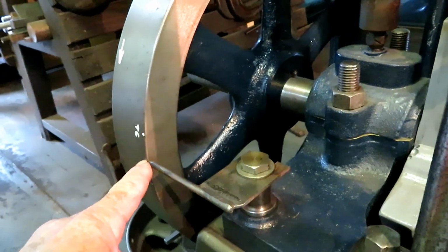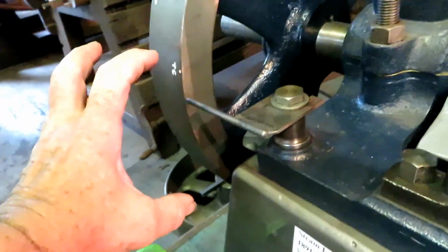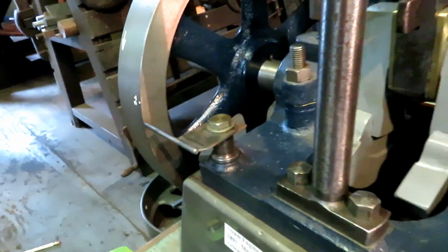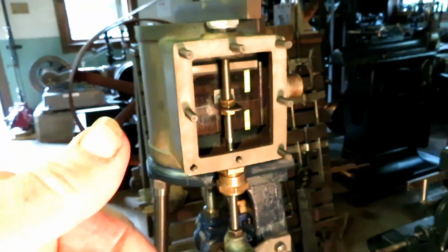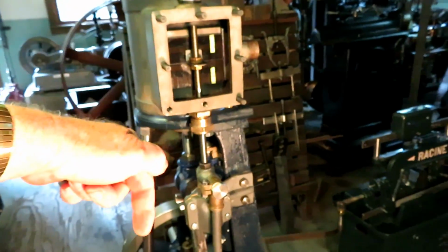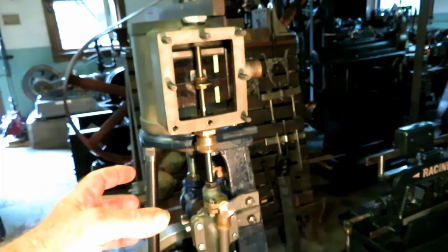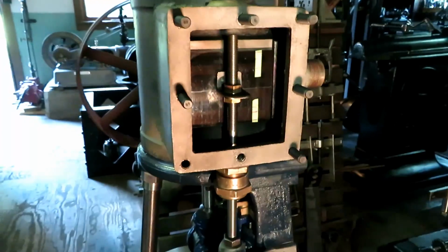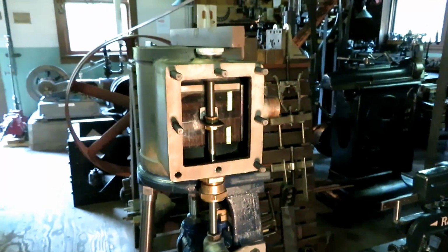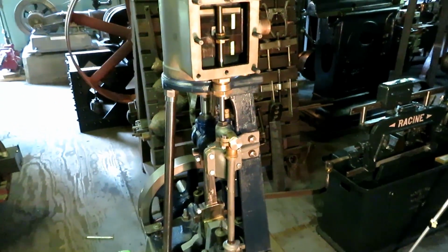So I've only got about that much cushion on the upstroke, and we had about that much cushion on the downstroke, even though the valve openings were correct. So you'd like to have a little more cushioning on the downstroke because you've got the extra weight of the crosshead, piston rod, and all of that stuff coming down. So you'd like a little more cushion on the bottom. But all things considered, the Bilgrim came out pretty good.